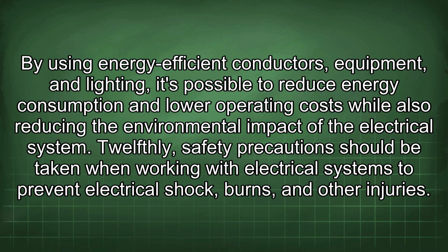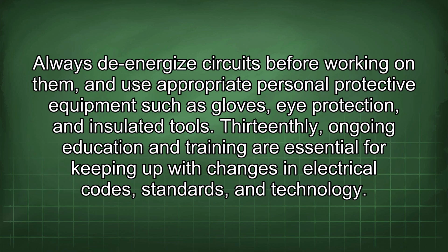12thly, safety precautions should be taken when working with electrical systems to prevent electrical shock, burns, and other injuries. Always de-energize circuits before working on them, and use appropriate personal protective equipment such as gloves, eye protection, and insulated tools. 13thly, ongoing education and training are essential for keeping up with changes in electrical codes, standards, and technology.